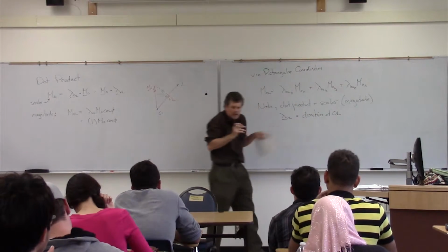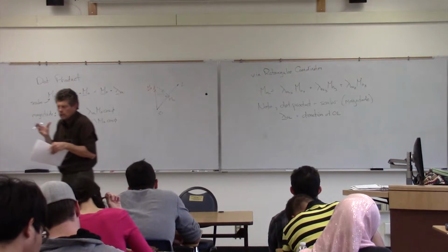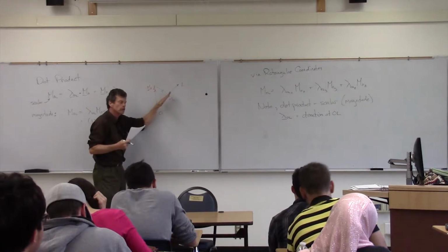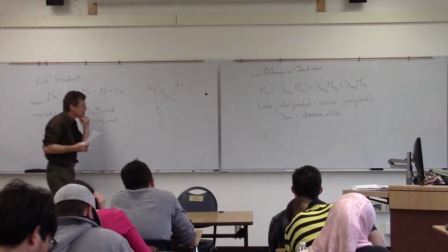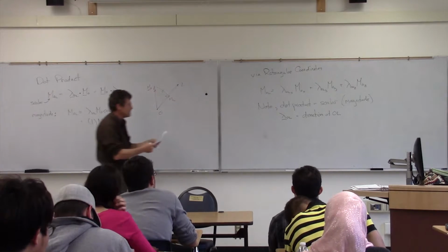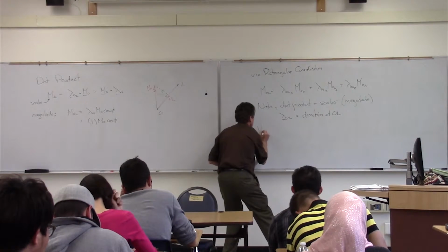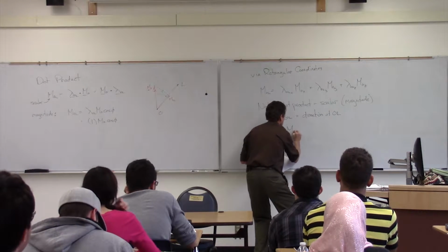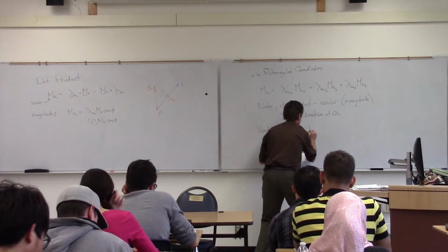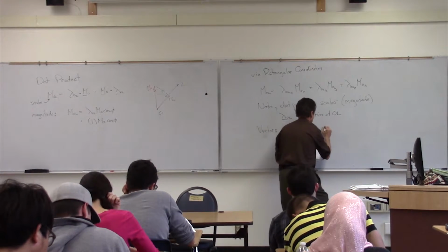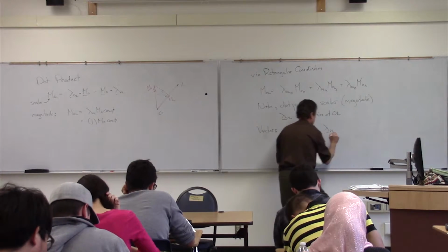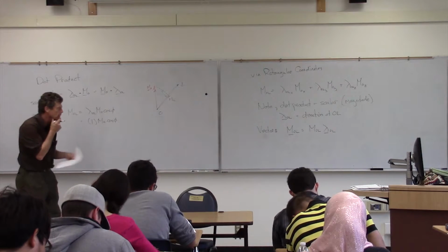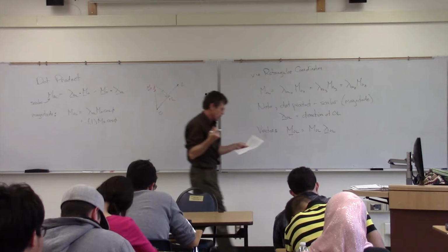But note that in order to get that dot product, we had to create this unit vector to get us there, right? We had to have a unit vector to project onto here to come up with that moment along OL. So there's no reason, if we want to express this as a vector, we've already got the direction. We just simply take a scalar times that unit vector again. Nice thing about that, then it breaks it up into the x, y, z components.